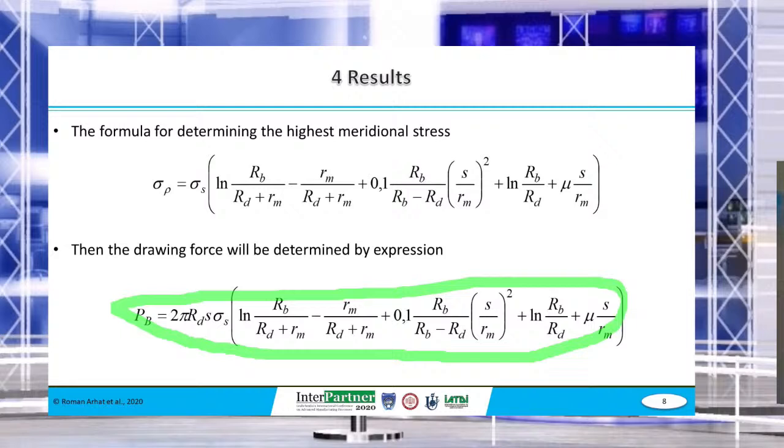In this drawing method, the calculation of the spring force is of decisive importance. Insufficient spring force will result in drawing only with the internal punch balls in the first stage, and in the second, excessive spring force will clamp both punches after the third stage and increase the pressing force of the external punch on the formed semi-finished product and can lead to a reject in the form of a separation of the bottom. Therefore, it is proposed, on the basis of research, to refine the formula in slide number 6.